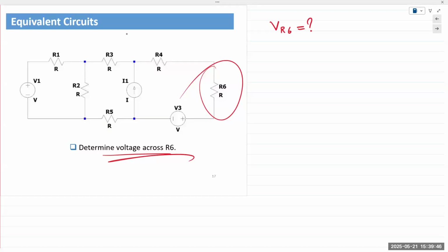Well, it turns out that VR6 is not within compliance. So let's say you need VR6 to be between, for instance, 5 and 7 volts, just random numbers. That's the requirement. You choose R6, you perform one iteration of your analysis, you choose R6 to be equal to, say, 100 ohms, and you obtain VR6 as 3 volts. So it's not within spec.